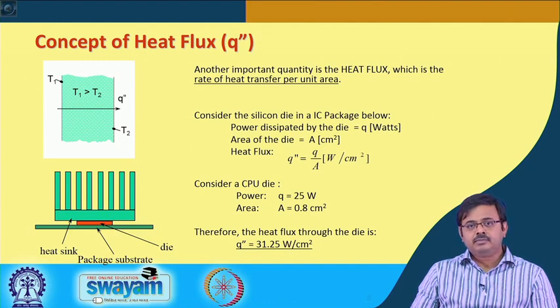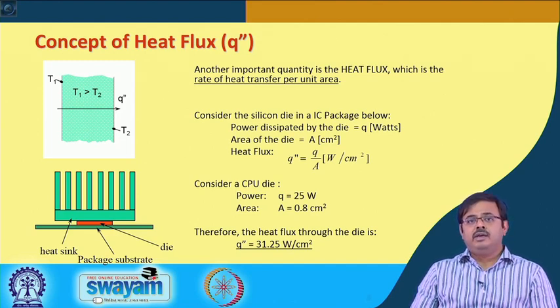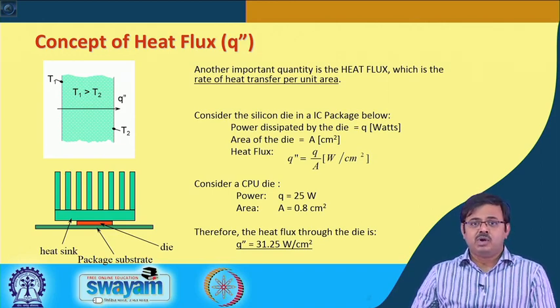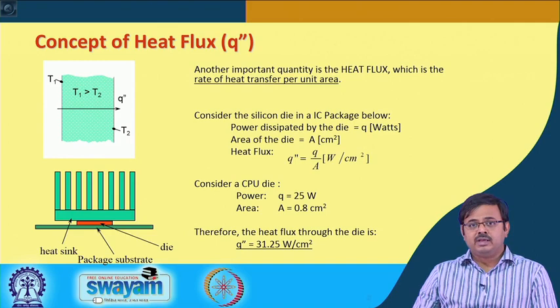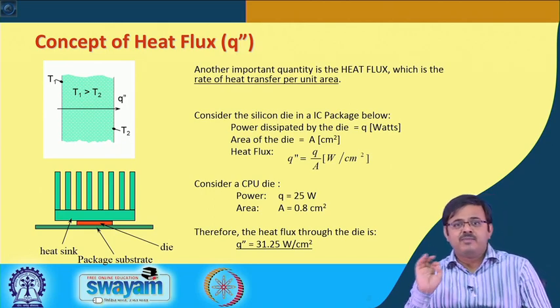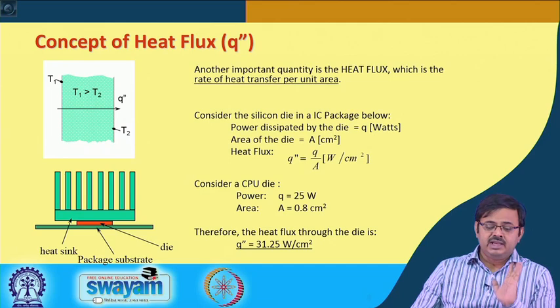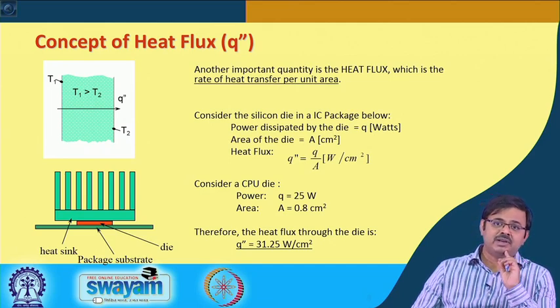So, whether I have to cool 100 watts over 1 meter squared versus 1 centimeter squared, the challenge, and therefore the technology that I need to deploy to achieve the cooling, is going to be very different. It is way more challenging. Why is that? Because of heat flux, which is heat dissipated per unit area.